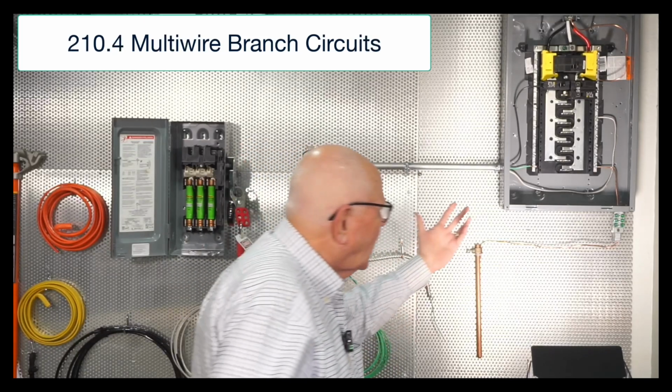I have to group those conductors. So if this were a multi-wire branch circuit, I would want to take probably my red and my black and my white, and I would tie them together. I could label them, whatever. Maybe it'd be easier, I'd just take a cable tie and put it on those three conductors, and that way they're grouped together.